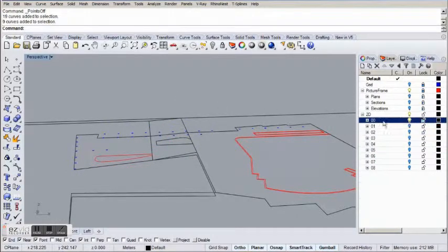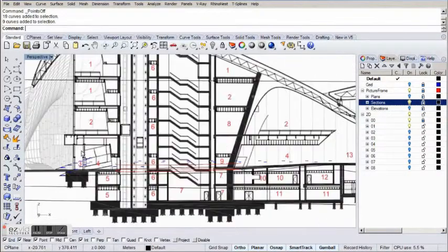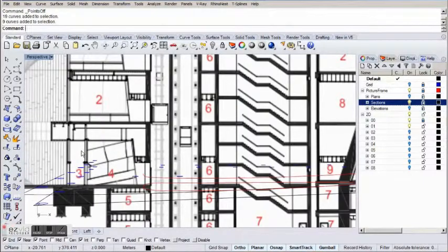Let's take a look at the first floor, at what height we need to place it. According to the section, the floor-to-floor distance is around 5.75 meters, so let's use this distance. A nifty trick to select the objects from all the sublayers within a parent layer is to right-click on the parent layer, in our case it's 01, and select the option Select Sublayer Objects.